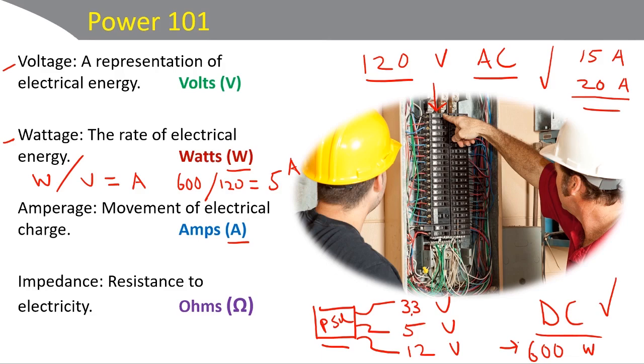The idea with the anti-static strap is that it helps with the release of static discharge through the strap and out to whatever you're connecting to as a ground. But if anything does happen to come back from that connection, then the resistor will help to protect you. And you might also test for continuity with cables. And you're looking for the zero resistance or 0 ohms when you do that. And I show how to do that in some videos with particular cables.